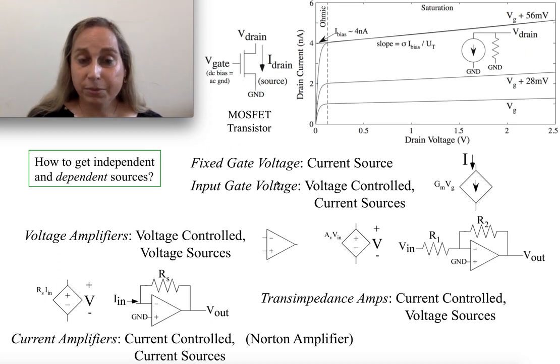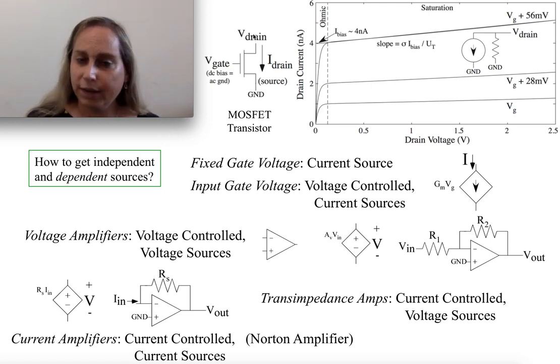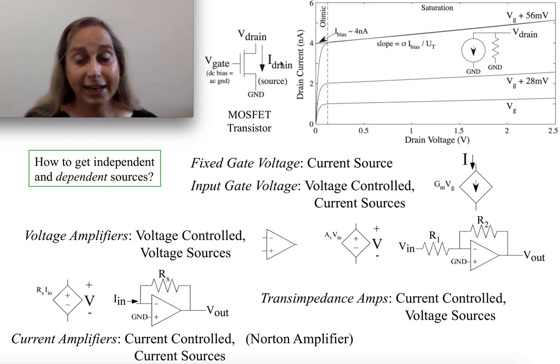What turns out to be really important, particularly if we look at a typical MOSFET transistor, and you could get a similar property with a BJT transistor, is this: I take the source voltage at ground, and the gate voltage is fixed, although I could put it at different fixed values, and eventually I can make it an input, but let's start with it being fixed. I don't fix the drain voltage, but sweep it through different voltages and then measure the current. I could ask, what kind of curves do I see?